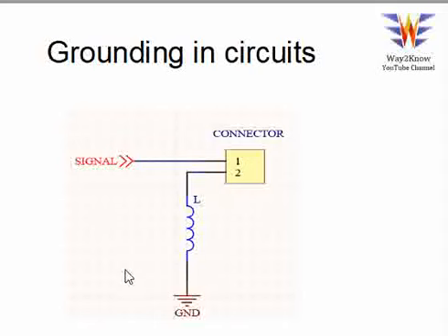A very simple implementation actually, but considering that most of the designers feel that the shield needs to be directly grounded, they do not implement this inductor mechanism. If you are facing EMI/EMC issues at your connector which is passing a signal outside, you try to implement this circuit and see if you are eliminating the radiation that is coming out of the cable.